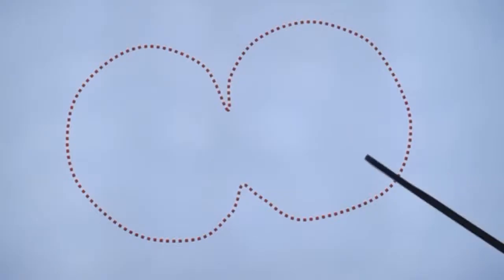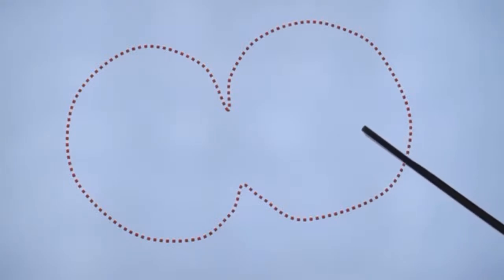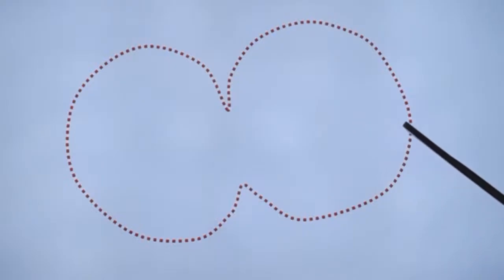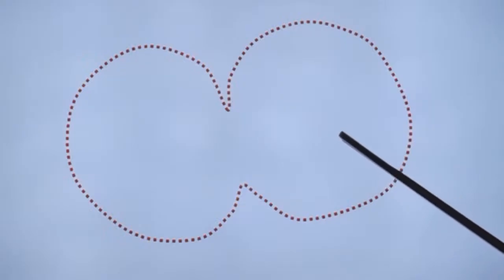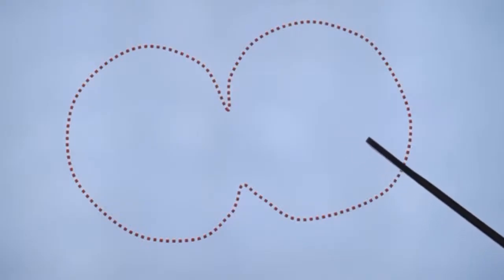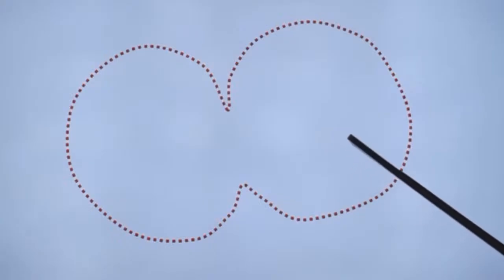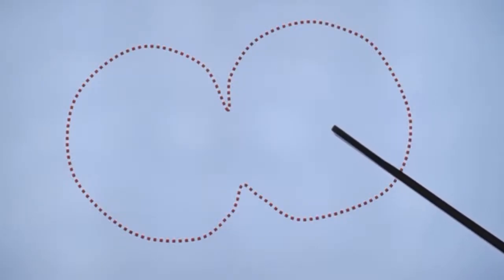So a rotator is not needed, or rather, the other way around. If you don't have a rotator, you can consider a J-pole as a compromise antenna for satellite operations. Then a single antenna for both UHF and VHF is also a compromise. Ideal would be to have two J-poles, one for UHF and one for VHF, and then connect them with a diplexer to the radio. But all this is getting complicated for a beginner in satellite operations.